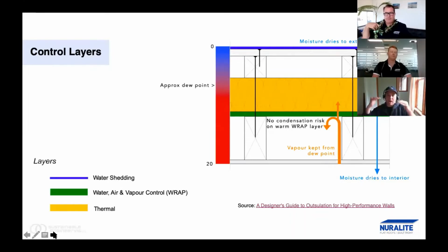And if the airflow rate's too high, you get the condensation even if you have good venting, right? So it's really common if you crawl around in attic spaces in colder climates, like in Queenstown, and you look at a normal vented attic roof, which has got a good, well-stopped gypsum board layer, but they put a can light in the bathroom for some crazy reason, which means they've got a big hole in the ceiling in the bathroom. And you'll see mold if they've got a rigid sarking, like an OSB sarking under the roof, because they've got an asphalt shingle roof in Queenstown, there's a few houses like that. We'll often have mold underneath on that OSB, because there's moisture coming up to that roof and hitting the underside of that roof and condensing, causing water and then mold.